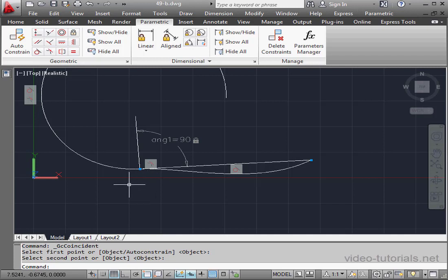The transition between surfaces created between the arc and the spline, which share both tangency as well as curvature, will be virtually non-detectable. And you'll be able to see how much smoother it looks when you apply some of the analysis tools such as the zebra stripes or the curvature analysis. This concludes our tutorial about curvature.